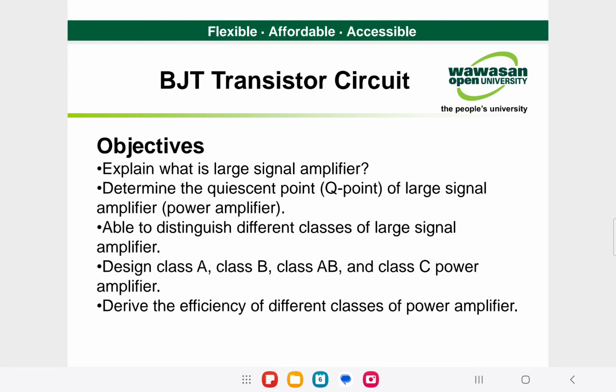Ideally the power amplifier would deliver 100% of the power it draws from the DC supply to the load. In practice, this will never occur because some of the components in the amplifier circuit dissipate power. Thus, we have a term named power efficiency.